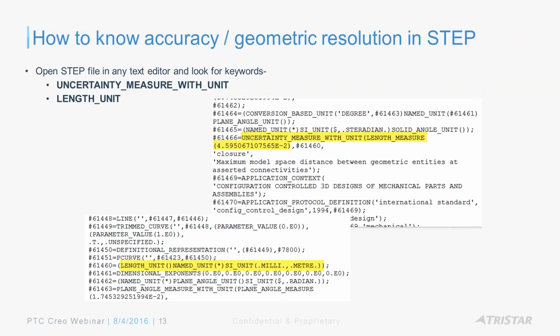Now, in my experience, when you use absolute accuracy, a lot of times I'm getting a better imported geometry. And the good thing is, if you change accuracy, as you know, it's not going to regenerate that imported geometry. It's just one import feature. When you create new features in Creo, that's when the accuracy gets affected, right? When you change the accuracy, new features will get regenerated, and it might impact that, but it's just an imported geometry.